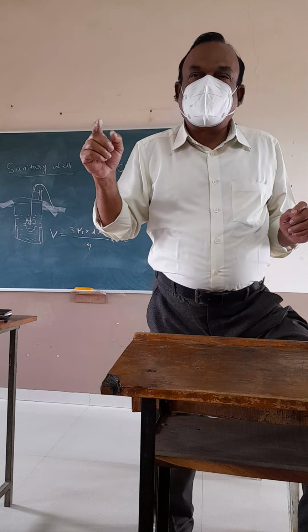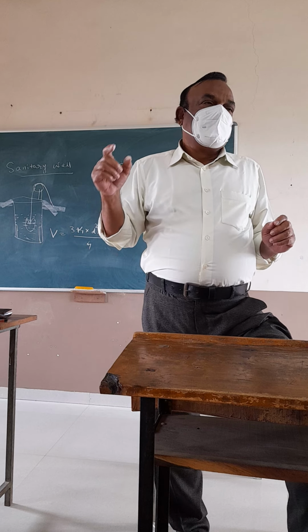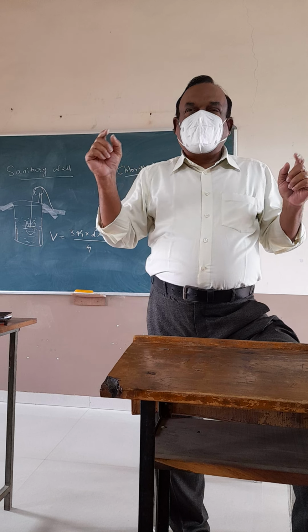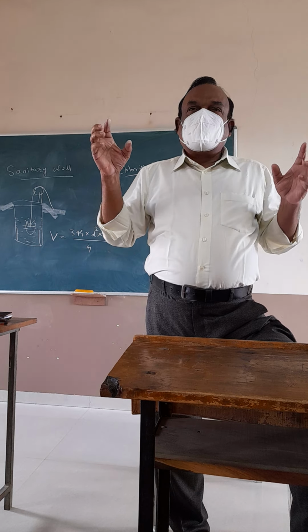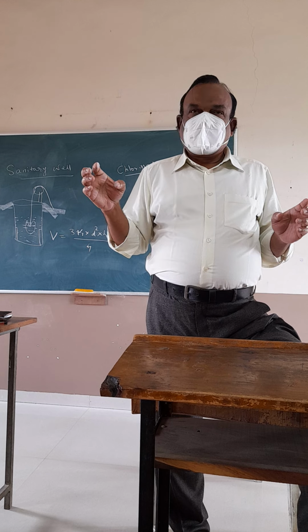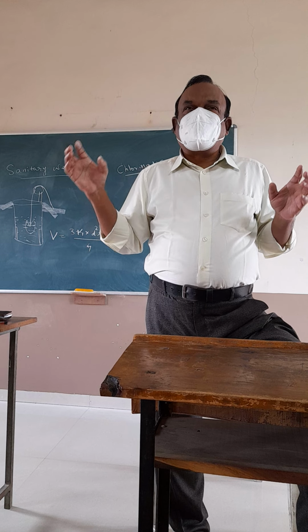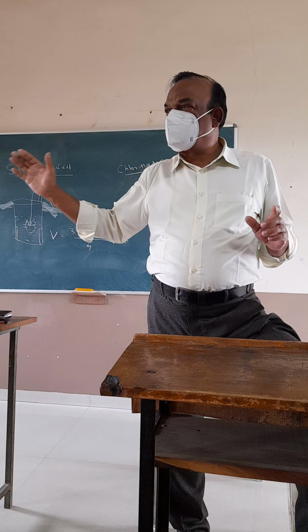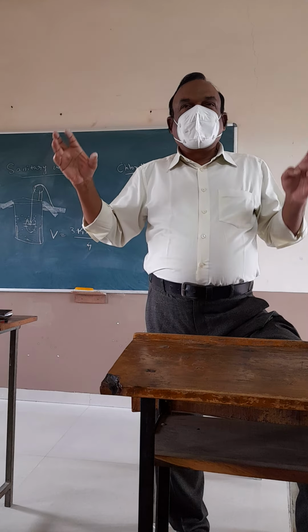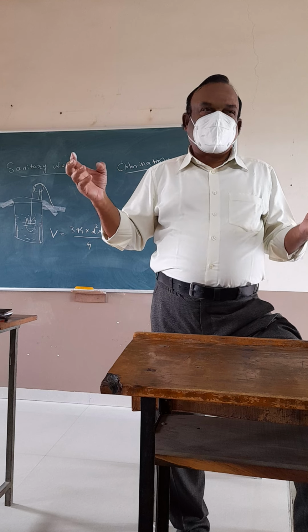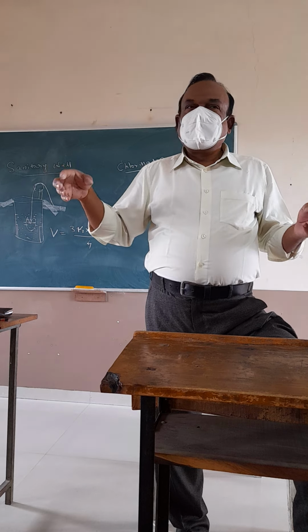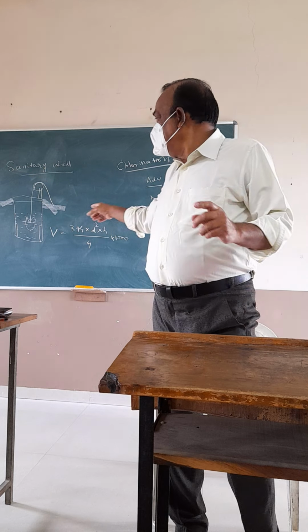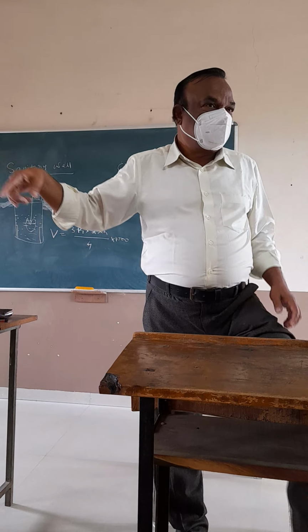What should not be closer to the well? Latrines or disposal sites should not be closer to the well. They should be 50 yards away from the well, because whatever liquid material is in the latrines percolates under the ground, and the same can drain from the bottom into the well.